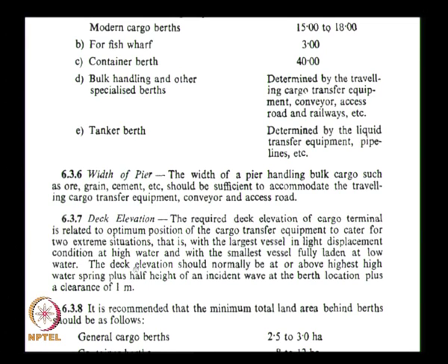This deck elevation, when we talk, we have to include the depth of the deck also. That is not very clear here, but please understand that the highest high water level plus half the height of the incident wave plus 1 meter clearance plus depth of the deck, we will have a deck beam and deck slab. So above that you have to provide the deck elevation.